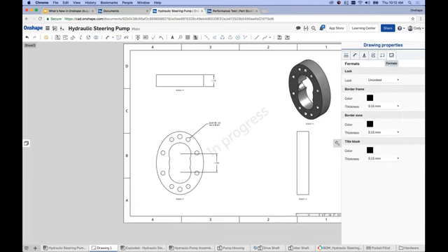And then finally, you have format options. The unlock and lock format option is here. Also, you can change things like the border frame color, the border frame thickness, the border zones and their definition, and the title block zones and their definition. So this is where you would set those format level options.